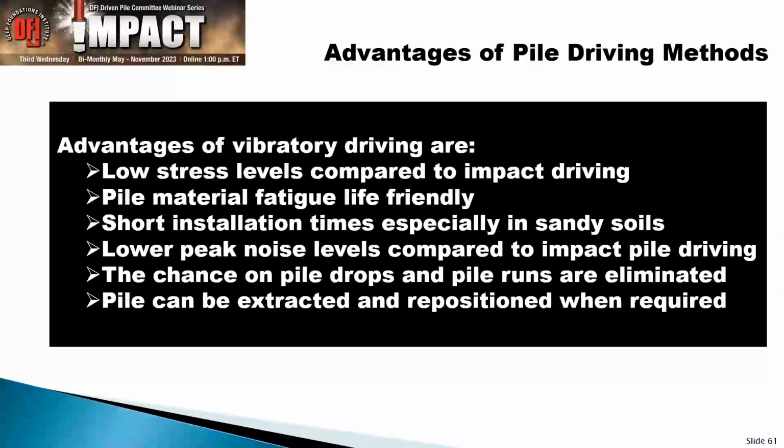You have low stress levels, and when it comes to pile material fatigue, not soil fatigue, but pile material fatigue, it is very friendly to use a vibratory hammer. You have extremely short installation times, especially in sandy soils: a few minutes, and you have a pile in the ground. Your noise levels are lower. And another important thing is that in vibratory driving mode, you have the pile hanging in the winch. So if something goes wrong, you can vibrate your pile again, pull it back out, and start again. That's not possible with an impact hammer.